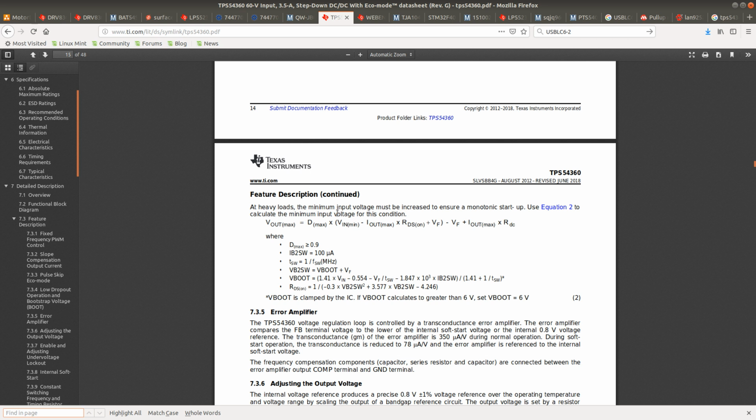And just any switching regulator, what happened there was that when the current suddenly increased during startup, the voltage increased slightly over 4 volts, and that was too much already for the module. Most circuits can handle voltages up to maybe over 4 volts. But in this case, the regulators on that module were not able to handle anything above 3.6 volts. So it was very important to keep the voltages down.